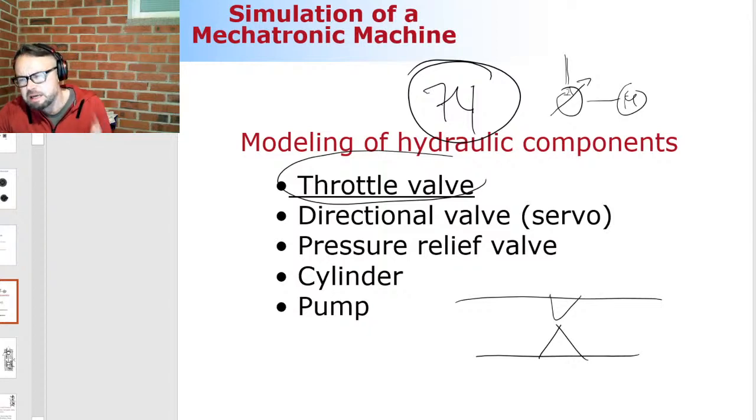And that's still what is happening in hydraulics. So if there is a direction valve, I'm going to make a simple drawing, sorry that this is a very low quality figure, but this is supposed to be a direction valve. So basically the control based on the direction valve is by introducing the pressure losses.